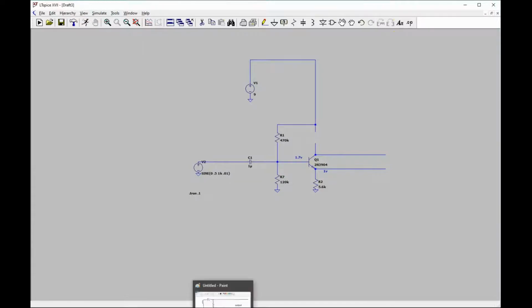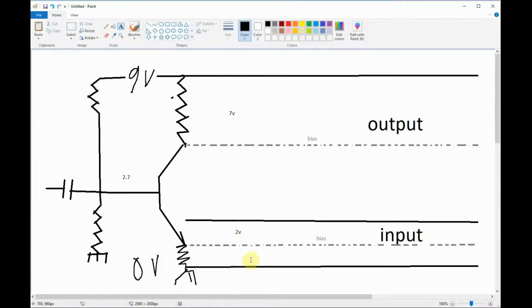All right. Now it's sitting at 1 volt, but that's where this thing is riding along. Let's look at this bad picture again. It's 2 volts, the whole range, but it's riding along 1 volt, right? Up and down there like that, because it's a sine wave. Anyways, you get the picture. This right here, the emitter follower, is at 1 volt, and it can take almost a 1 volt negative swing, almost up to 2 volts there. And so this one here, you've got 7 volts left.